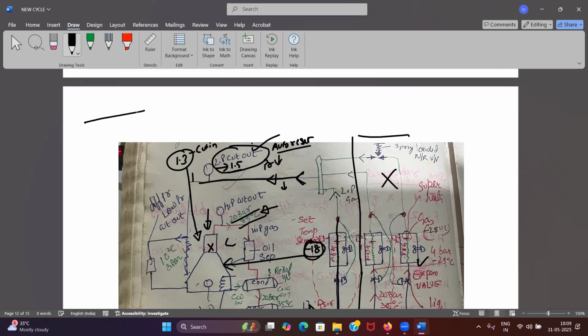That means now I can give any cooling medium which is less than 85, and it will condense. And I have plenty of seawater on board. So seawater will be able to condense this vapor refrigerant. Is it clear?